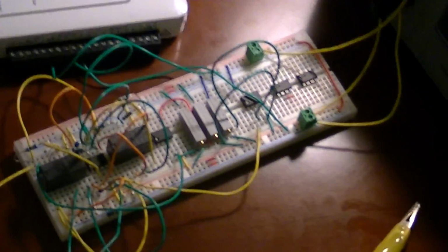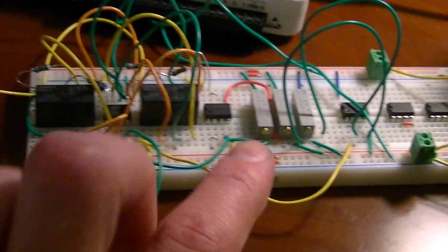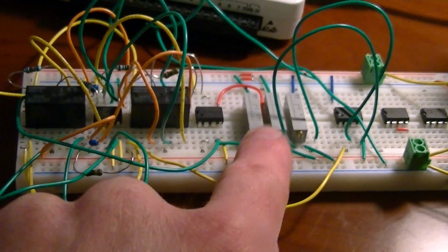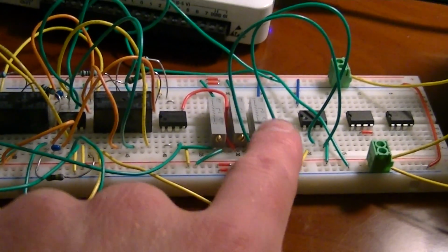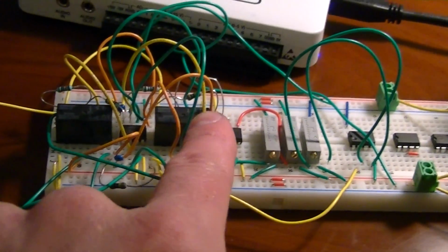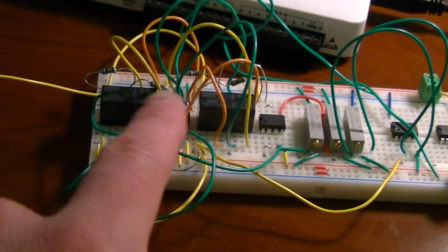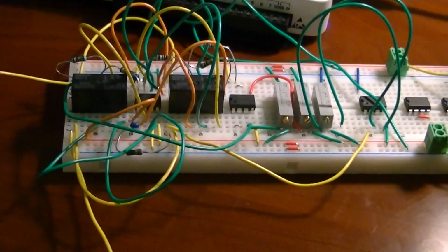Hello, I wanted to document a recent project of mine, and I know it's a bit messy, but it's this circuit right here. How this works is it can solve the falling body problem. This potentiometer here is the initial velocity, this potentiometer here is the initial position, and this one is the force of gravity. This is the first integrator, this is the second integrator. It's on this chip actually, and the capacitors you see on both sides set the initial conditions.